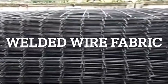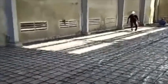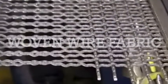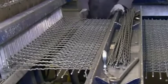Welded wire fabric, a grid of longitudinal and transverse steel wires or bars welded together at all points of intersection, usually specified by the size of the grid in inches and the wire gauge, also called welded wire mesh. Woven wire fabric, a mesh of cold-drawn steel wires mechanically twisted together to form hexagonally shaped openings.